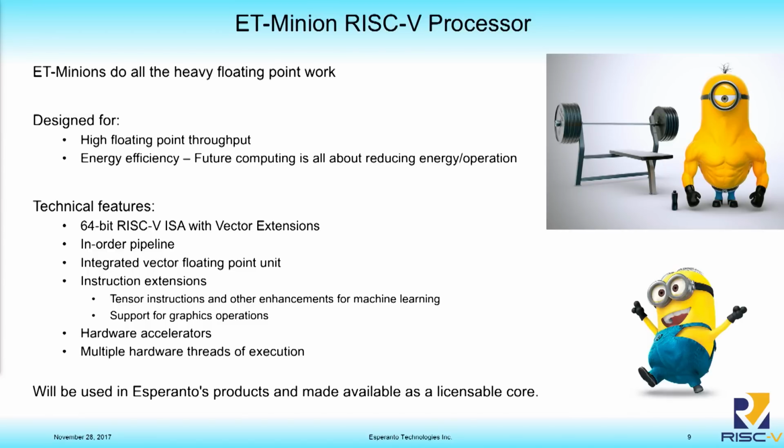So what we're building is, again, a full 64-bit RISC-V ISA, but this little Minion is going to have its own integrated vector floating point unit. And we're going to do the full vector instruction set, but as we're looking at areas like machine learning, we've added some instruction extensions. So one that we think isn't quite defined yet by the vector unit is good support for tensors. So we're prototyping this, and when we feel we get it right, we'll talk more about that. But we found that helps us with our energy efficiency, and we couldn't resist.